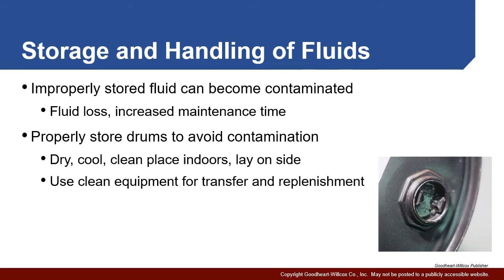Drums are designed to be laid on their side. It's essential when you're transferring or filling the fluid that the environment be clean, and that you use proper filtration to avoid any type of contaminants getting in, right? So all that needs to be done. Not only does it keep the fluid clean, but it also prevents it from evaporating or leaking, etc.